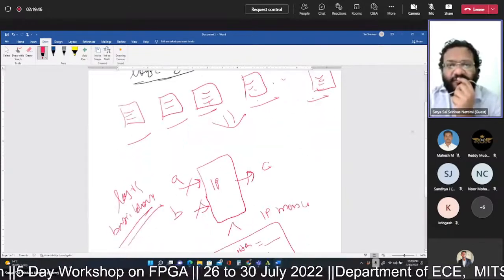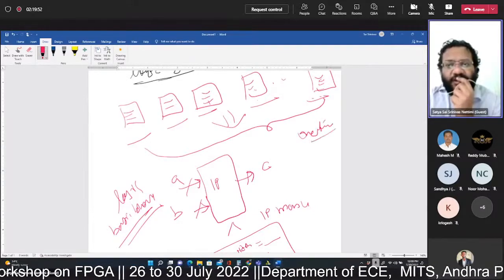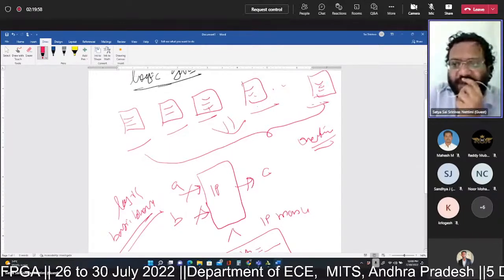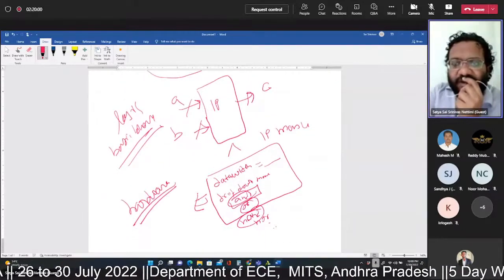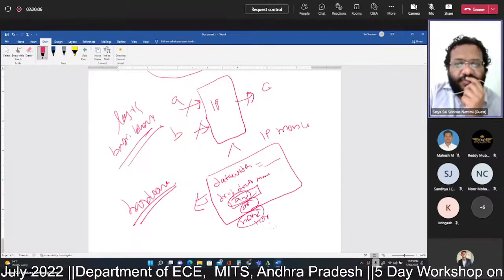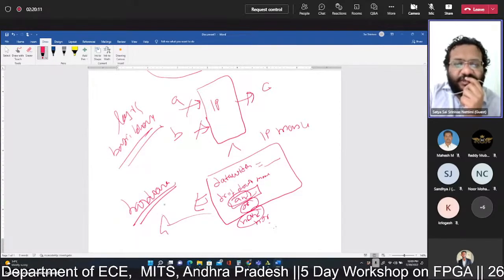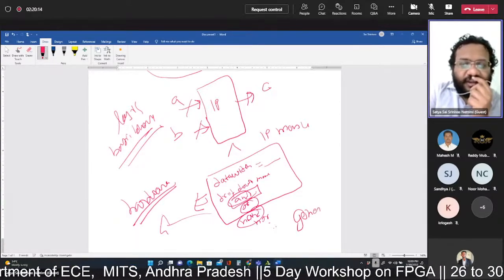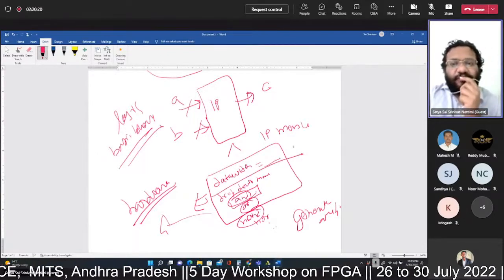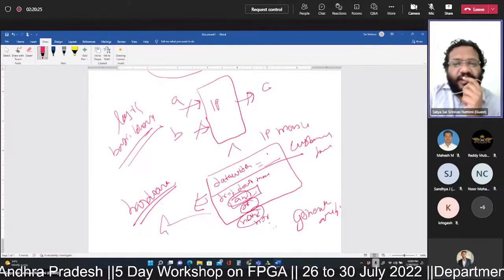So instead, I will put in the effort only one time. In that one time, I will club everything in the form of an IP core and package it. Then whenever I want to use it, I'll just call my IP and customize in my IP menu what architecture I want to generate, and it will generate that architecture. So this is the second concept, generating the architecture. And how is it generating? First it takes the customization parameters on top, and then it generates accordingly.